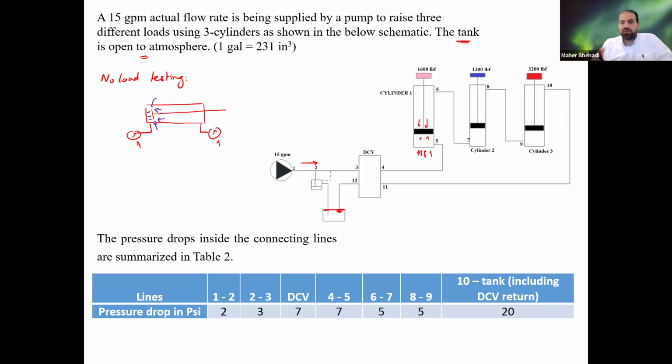So in the first part, when we will be calculating the friction loss, I don't need to include any of these three loads, W1, W2, and W3. That's part of how we find the supply pressure for each cylinder. In this case, the supply pressure that would supply the three cylinders, because they are connected in series.